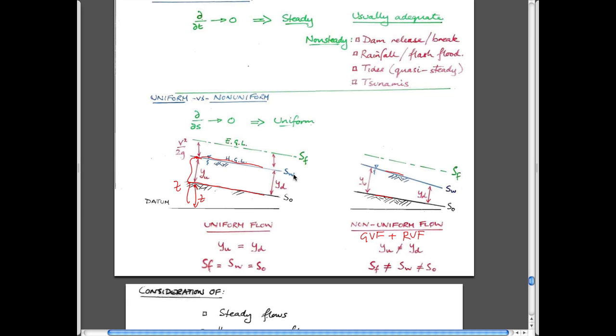This would be the location downstream. This would also be some magnitude where this is the elevation, if you like, elevations 1 and 2. Again, this is on the free surface, so this magnitude is equal to the elevation. The thickness of the pressure is 0, so P over gamma equals 0 on the surface. And so this hydraulic grade line would be exactly parallel to the free surface of the water, which is also parallel to the bed, which we've stated is the requirement for uniform flow.